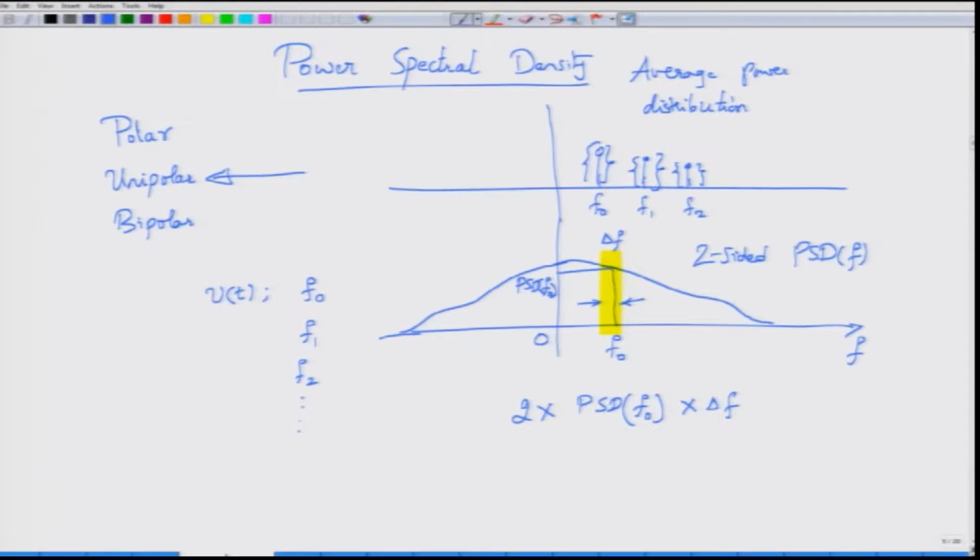In fact, when we talked about noise, we wrote some spectral density formulas. We said the noise associated with a load resistor RL has a power spectral density of 4kT by RL. If you then consider a particular band of frequencies with a bandwidth of B centered at some f0, the power spectral density is flat, it does not depend on f0.